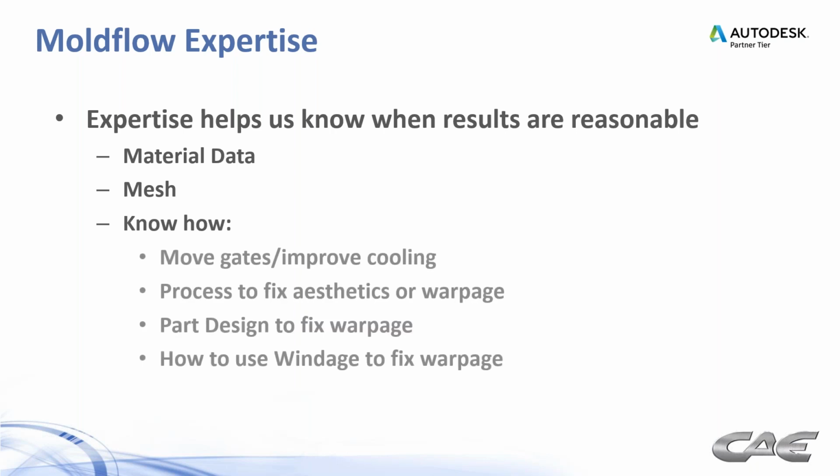And then expertise involves know-how: knowing how to move gates or how to improve cooling by moving water lines, knowing how to process to fix aesthetics or warpage, knowing how to change part design to fix warpage, or how to use windage to fix warpage.